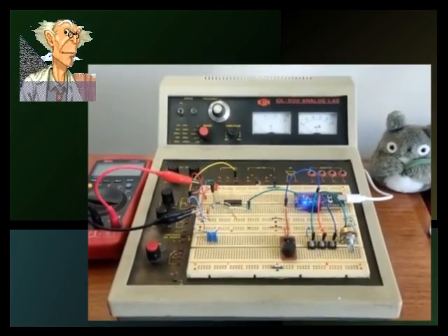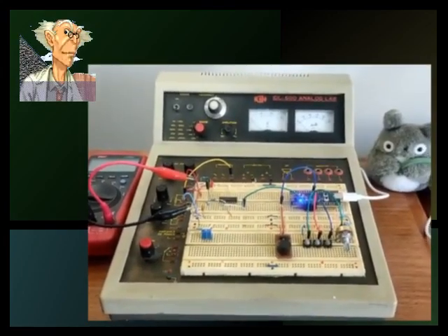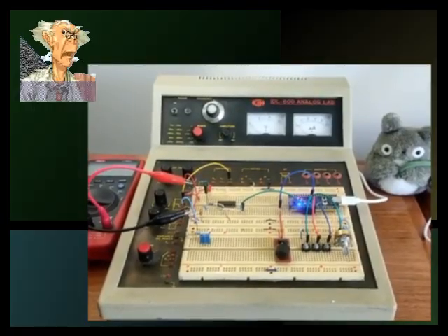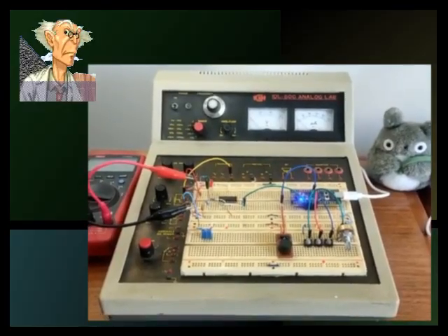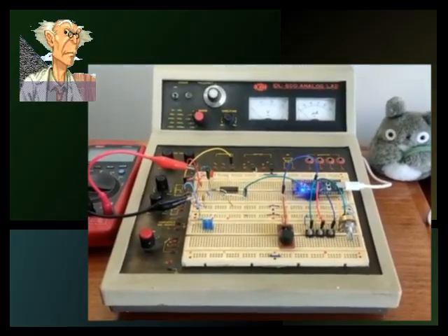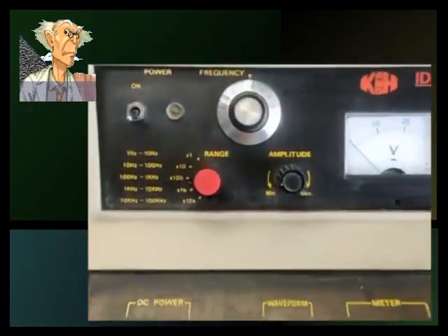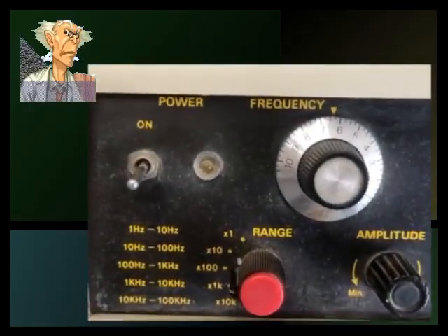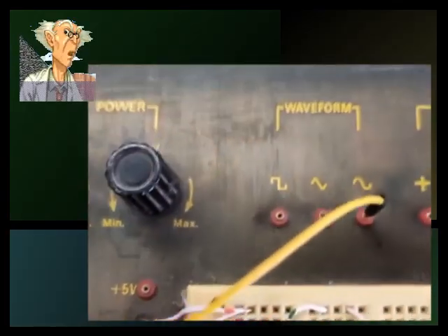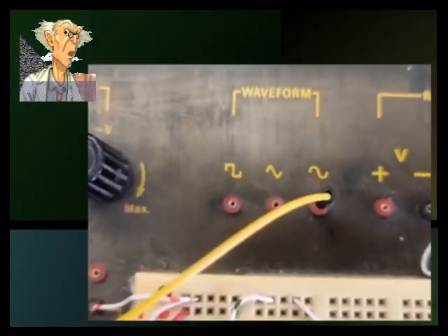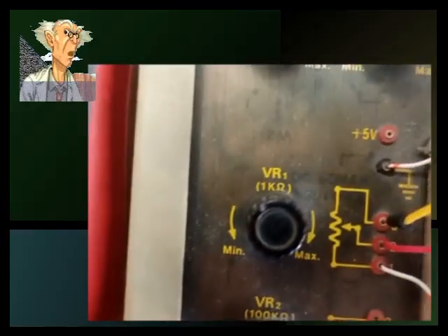Hi everyone. In this session, we're going to review a homemade oscilloscope built around the STM32F401 microcontroller. For the development, we'll be using a lab breadboard that includes a signal generator, which will be very useful for our purposes. The generator can produce square, triangular, or sine wave signals, and its amplitude is adjusted through a potentiometer.